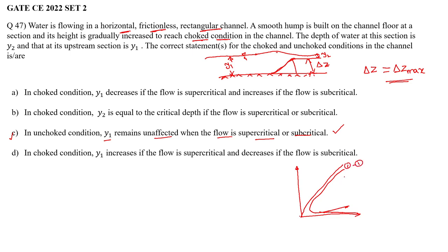Now let's say if the choked flow happens, the curve will shift towards the right. This is let's say E minimum, and this is E2. Now the curve will shift in such a way that E2 will be equal to E minimum, and this is E1, and this will go to E1 dash. Maybe this is slightly confusing for you. Don't worry, you will get to it. It's simple and straightforward. This is initial. This is secondary. This is for a choked condition.